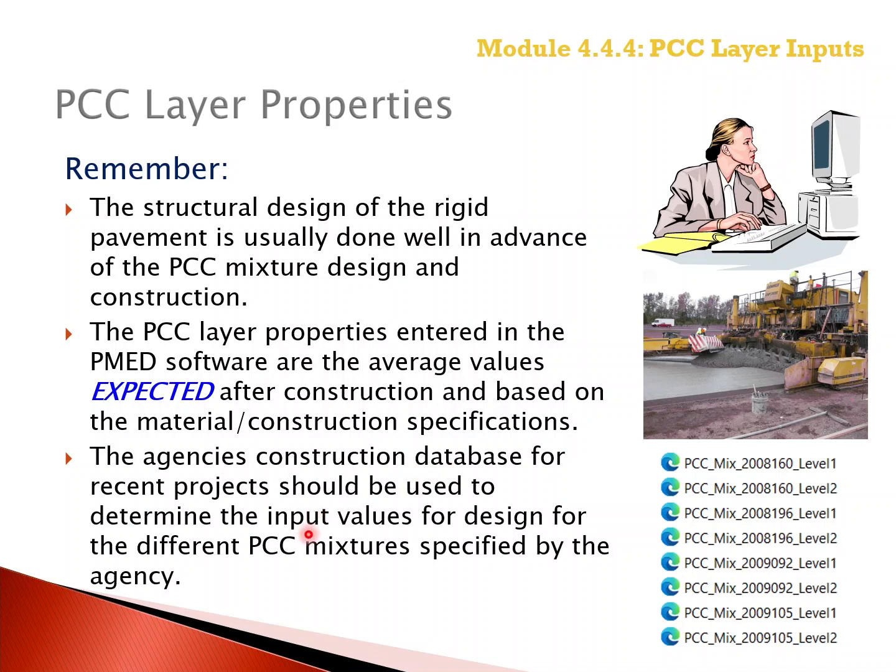Many agencies have created, from that data, PCC XML material files or material library files for the concrete mixtures included in their construction specifications. This allows the designer to select a concrete mixture when completing the rigid pavement structural design with confidence. So the importance of these XML material libraries really cannot be overemphasized.